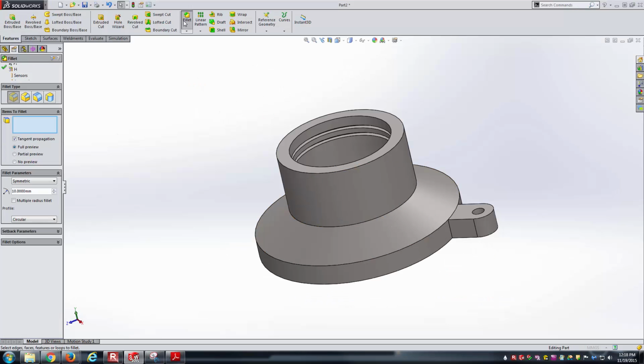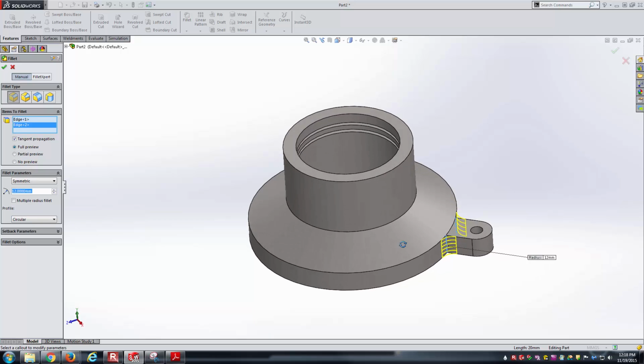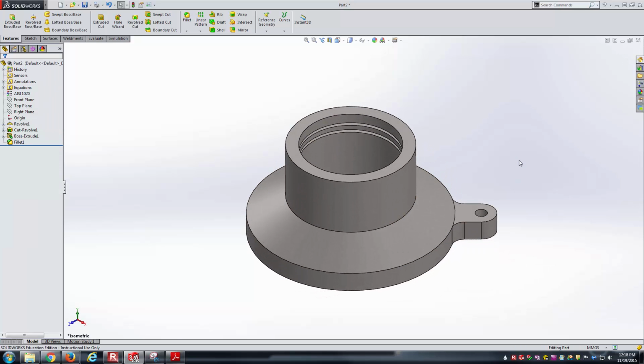Let's go ahead and add those as feature fillets. So just going to the simple fillet type, putting in 12 as the radius and selecting those two edges in order to define it. So now that I have that, we're ready to actually pattern it. And so right under the linear pattern is of course circular pattern.